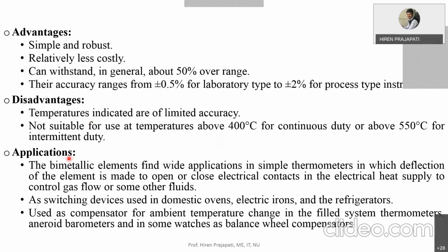Now their applications. Bimetallic elements find wide application in simple thermometers in which deflection of the element is made to open or close electric contacts in the electrical heat supply, to control gas flow or some other fluids. This is not the application of the bimetallic thermometer as a whole, but of bimetallic elements.